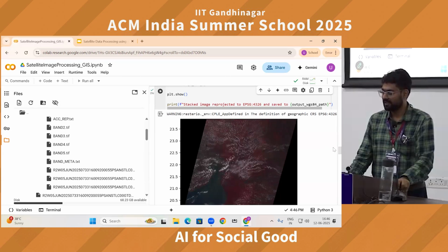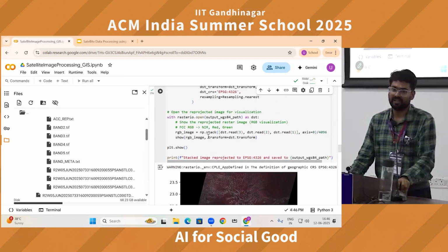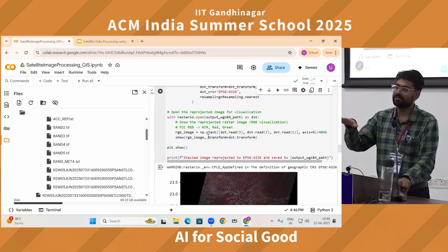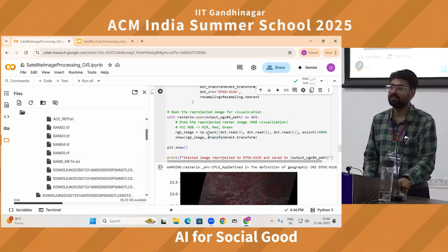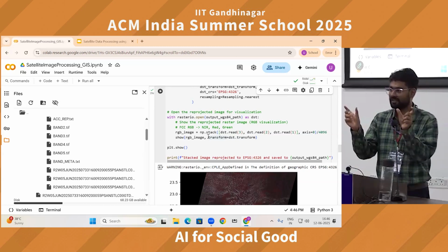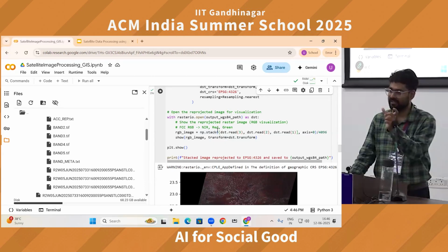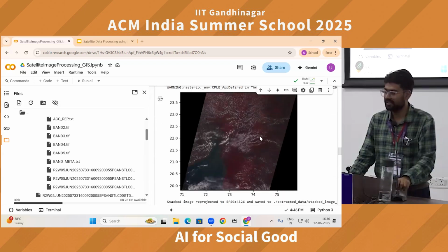Okay. So there is a term called false color composite, where we give red color to that particular band which gives us more information. So in case of vegetation, NIR has high variability in terms of data, and therefore we give red color to the NIR band. Similarly, we give green color to the red wavelength, basically the red band channel, and blue color is given to the green band. And that is why we see here in this image the vegetation in red color.